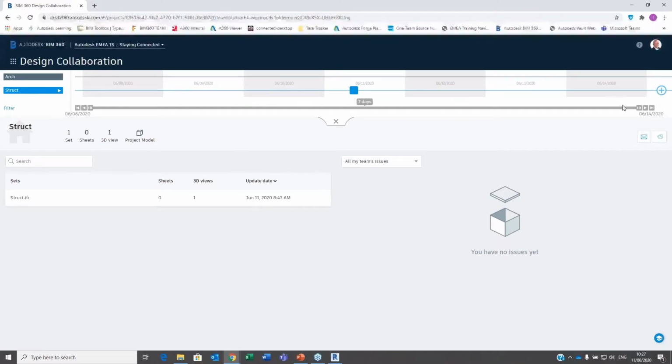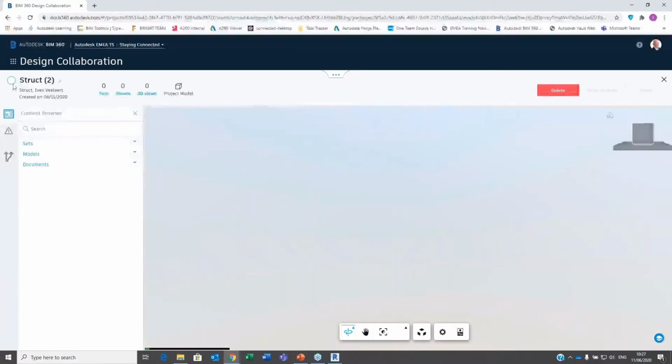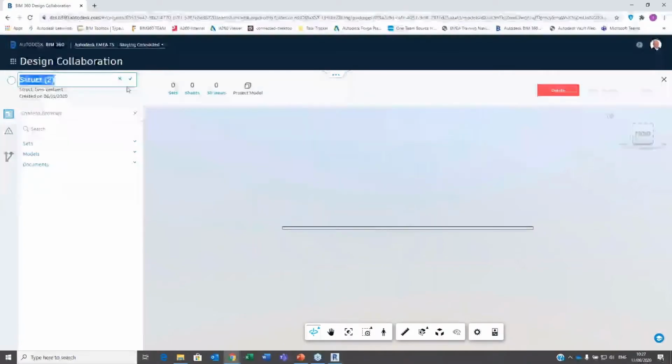So what I'm going to do here is I'm going to open up this IFC file for the architectural team. So essentially, it means that I'm going to create my package. And so packages are very specific to BIM 360 design. So I'm going to click on a package here, and I'm going to say, right, first drop or something, first milestone, whatever.